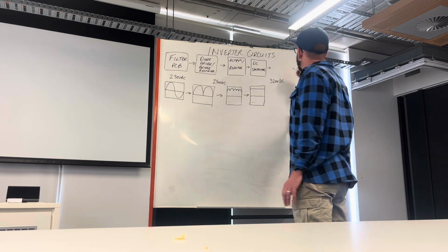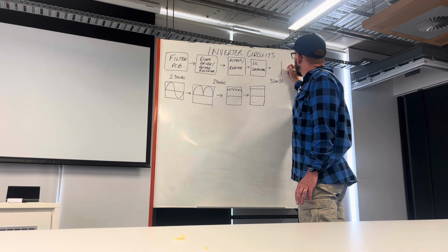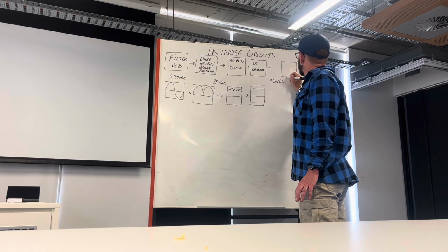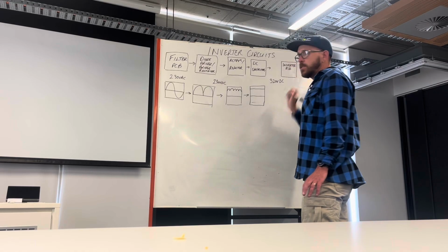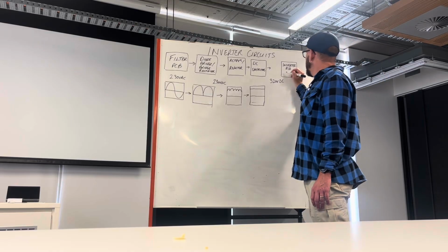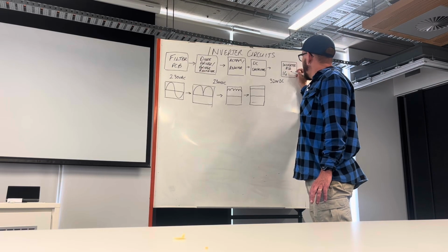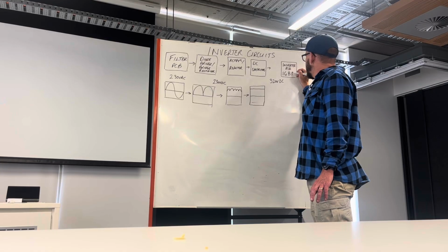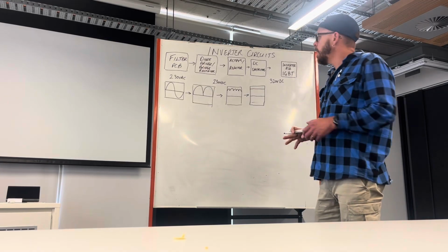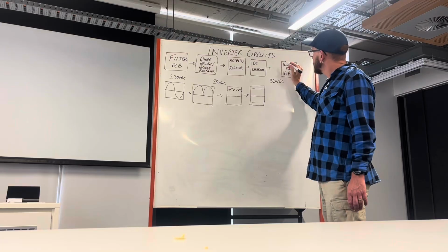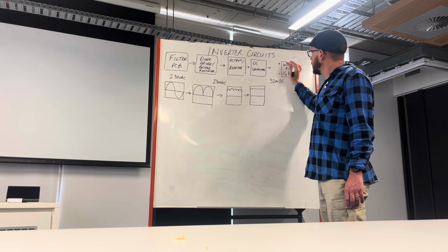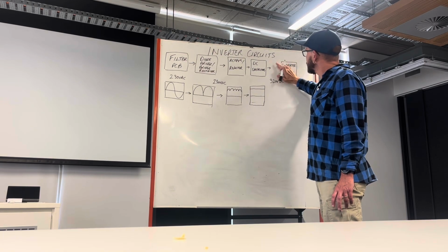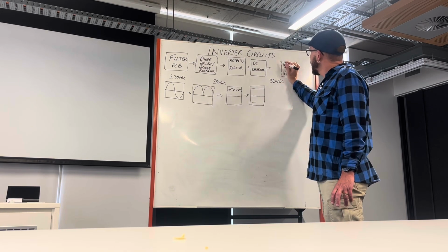So the next stage is our inverter PCB. Some brands call this a IGBT, insulated gate bipolar transistors. Basically what we have here is our 320 volt DC coming in, so positive and negative. Sorry, I'll draw that. P and N.